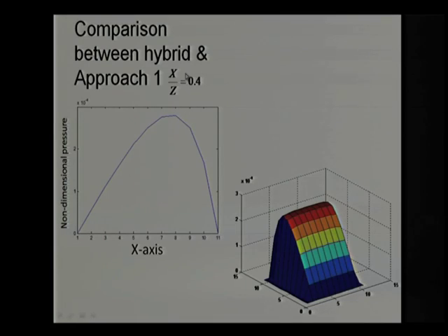With the hybrid approach, we get a quick solution, and we do not discretize or divide into a number of domains, obviously a number of nodes. So, the hybrid approach has an advantage from that point of view, and finite difference from the accuracy point of view. We can compare the hybrid approach pressure expression with the finite difference method, that is going to give us some confidence. Of course, in this slide we are showing that even when x is equal to 40%